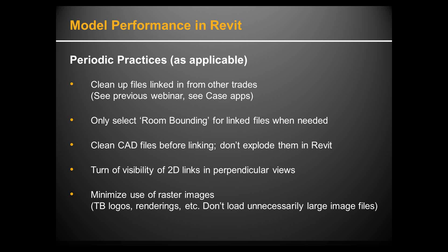Second item, room bounding for MEP. You're going to need this. But if you don't need it, if you don't care about the room bounding, you might want to uncheck that. That's something that causes Revit to do more calculations in the background.